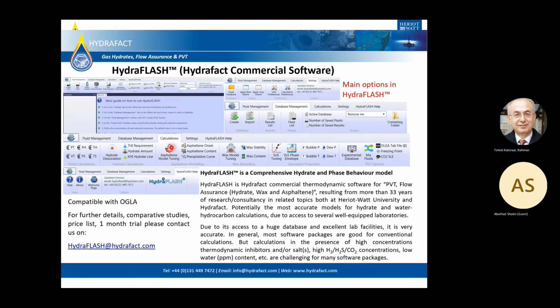Asphaltene model tuning, asphaltene onset, asphaltene content, precipitation curve, wax model, wax stability, wax content, and then equation of state tuning. If you have experimental data, we can tune the equation of state, and we can plot the hydrate phase envelope.